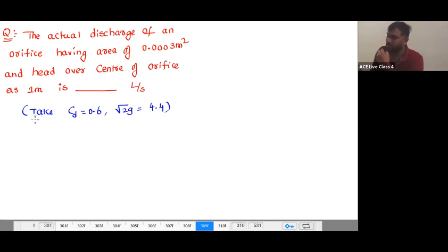The answer is going to be 0.972. See, I am asking you the actual discharge of an orifice, which means CD into A into root of 2gH.